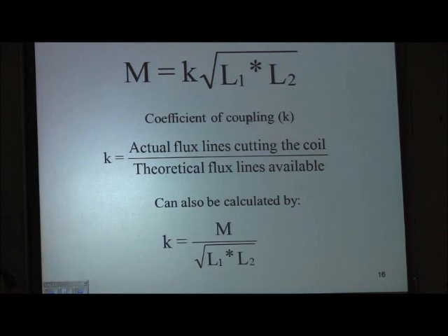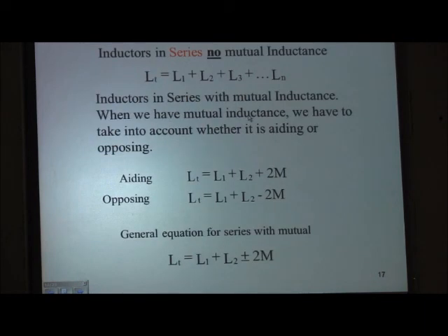Mutual inductance equals our coefficient of coupling, which is right here, times the square root of L1 times L2. We'll only give you two inductors to figure this one out. Okay, and we have to give you either M or K. So we give you K, and you've got to find, two inductors in series, aiding. You've got to get M and then find total inductance.